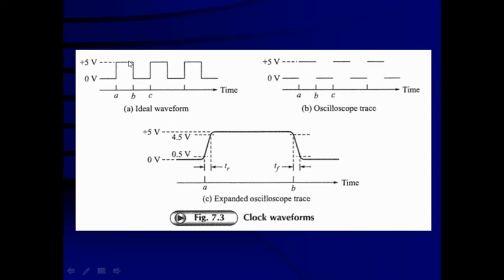It should not fluctuate this way. Whatever that voltage level is, it should be exactly stable and unchanging with respect to time. Between B and C, it should be exactly 0 volt. Even if it is 0.2 volt, it is acceptable, but it should be unchanging 0.2 volt only.